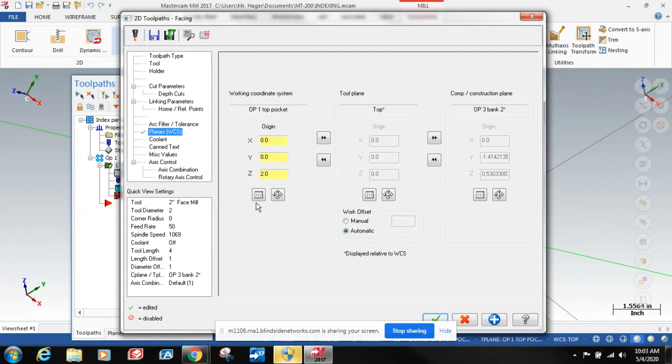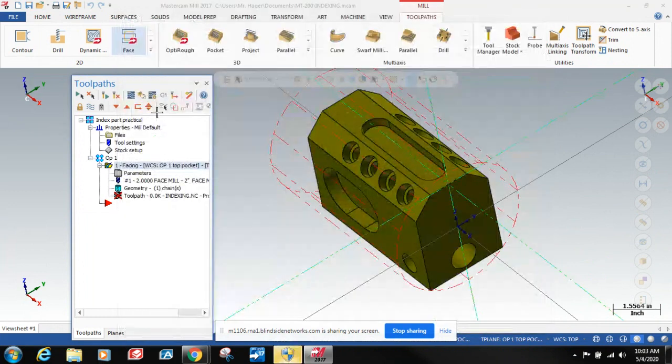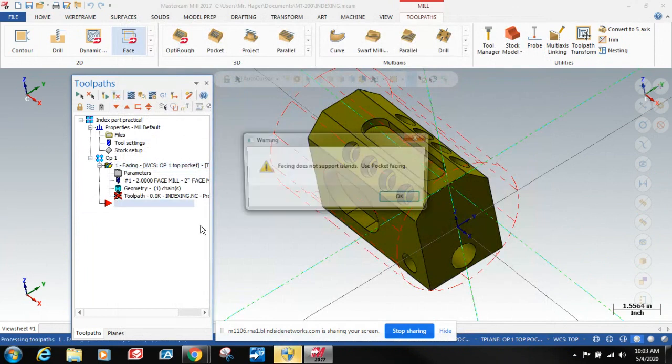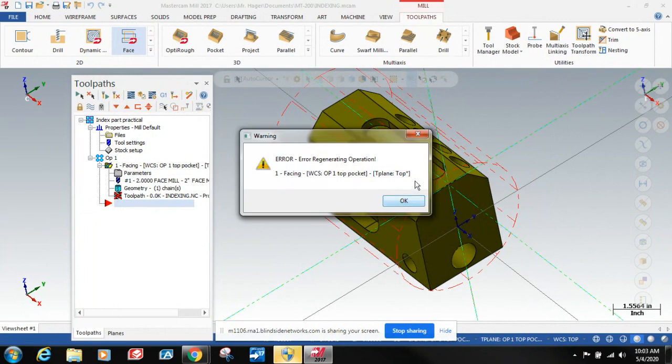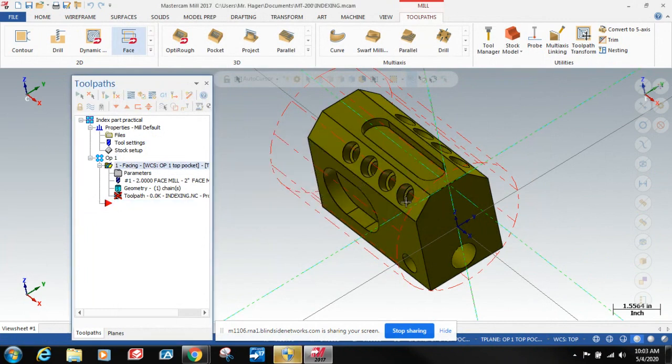Yeah, well, you could also have the computer do it for you, like depth cuts. Yeah, that's what I meant. That's what I'm having it do. But I don't know how high the feed plane should be, so I'm gonna make it ½ inch and see what happens.